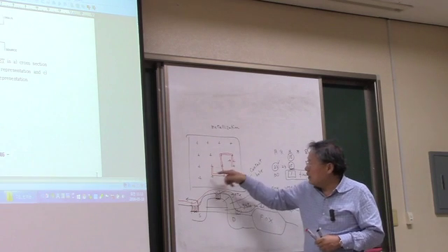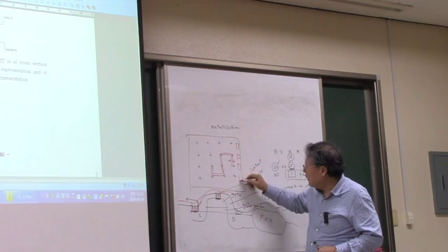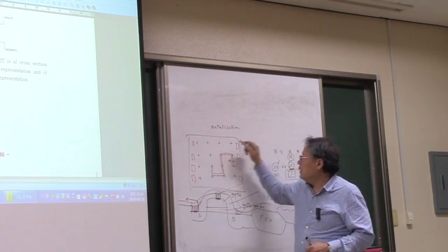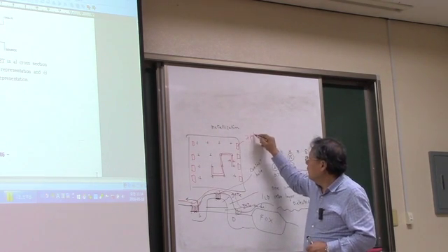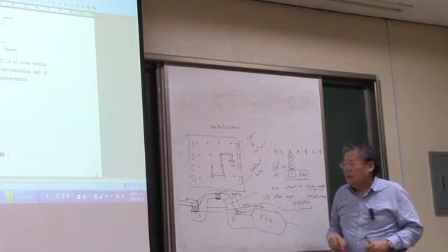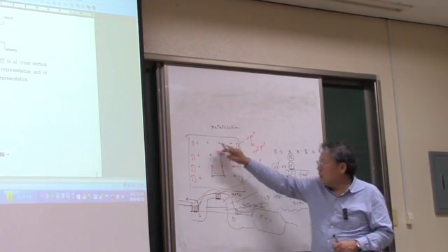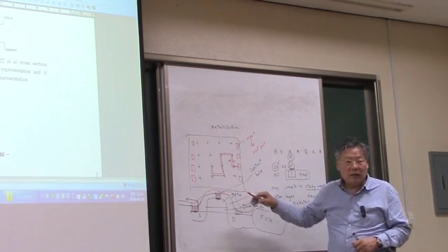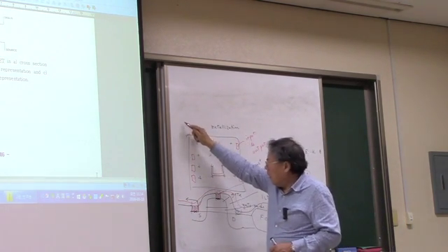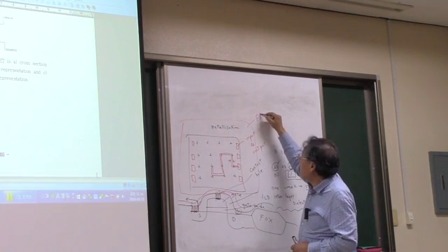And when you make the circuit, you also form a pad. We call this pad. Okay. This pad is for the input and output. This pad is connected to the metal lines that we have formed inside these integrated transistors. And with this pad, after the metallization, we do the passivation. We call that the passivation.